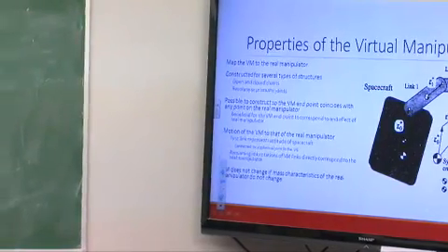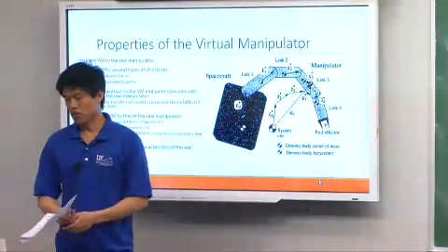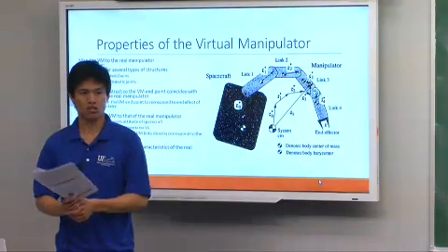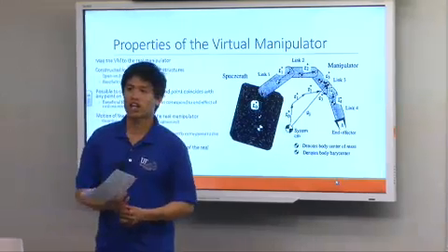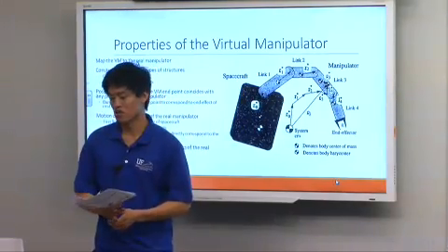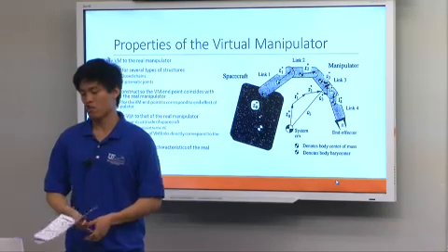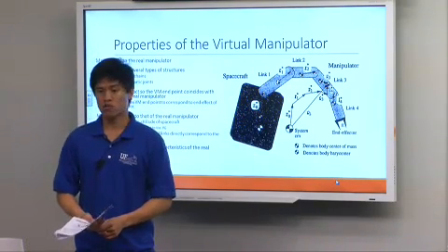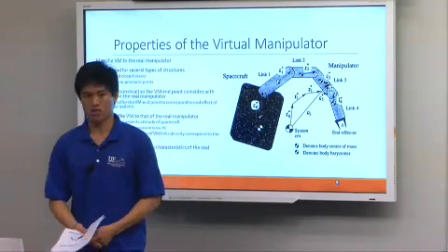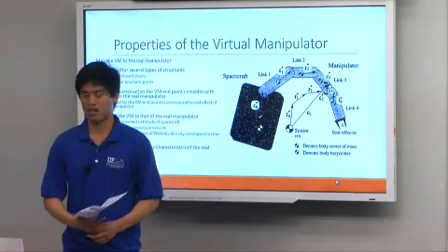An important point, I want to stress this again, is that the virtual manipulator just maps the motion to the real manipulator. And the person who came up with this has shown that it can be constructed for several types of structures: open and closed loop chains, and revolute or prismatic joints, typical of a normal robotic arm manipulator.